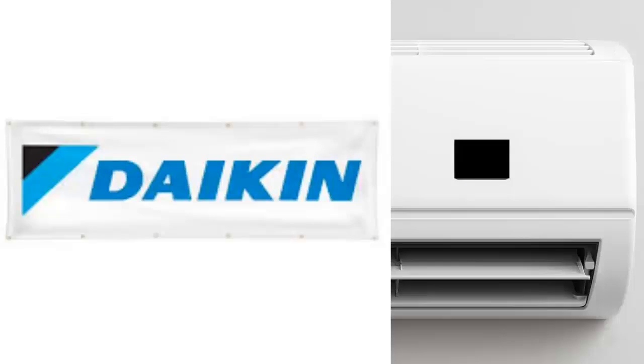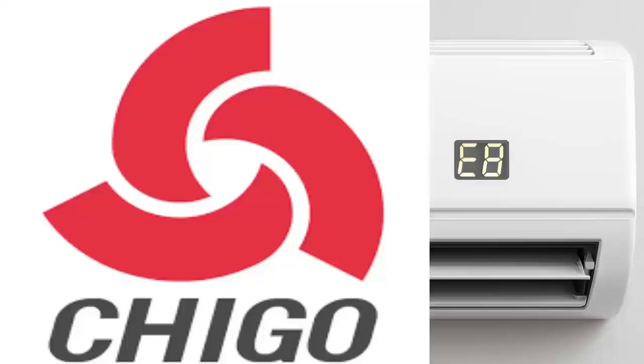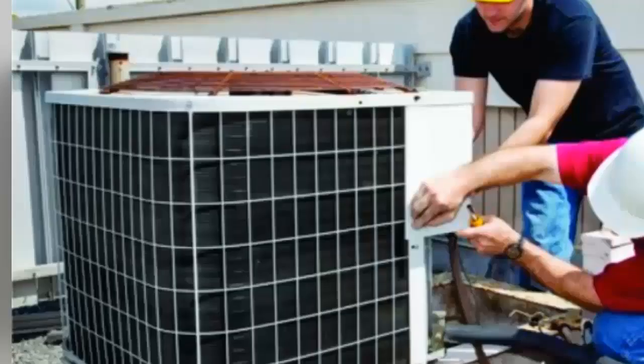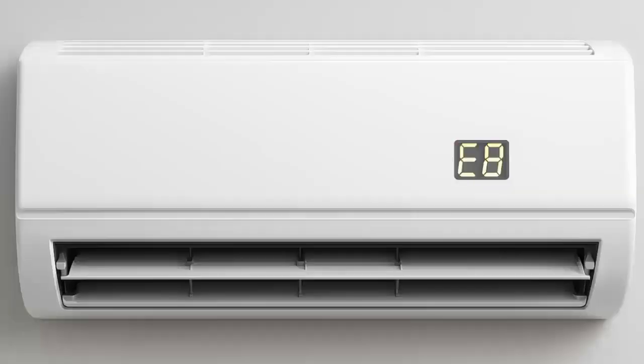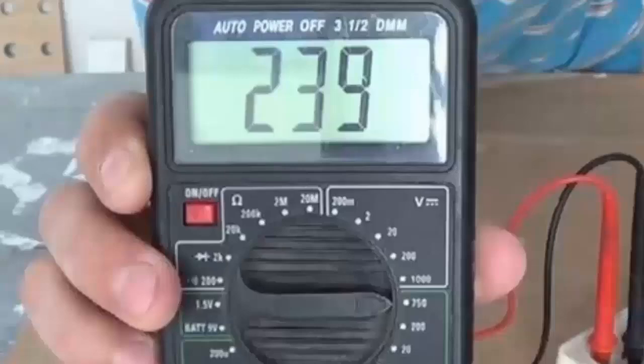Brands where this occurs: Daikin Commercial, inverter compressor overcurrent. General Electric window unit, compressor overload. Chigo, overheating protection. Steps to follow. A. Check the cleanliness of the outdoor unit coil and the proper rotation of the outdoor fan. B. Measure the power supply voltage. If it is unstable, consider using a voltage stabilizer.